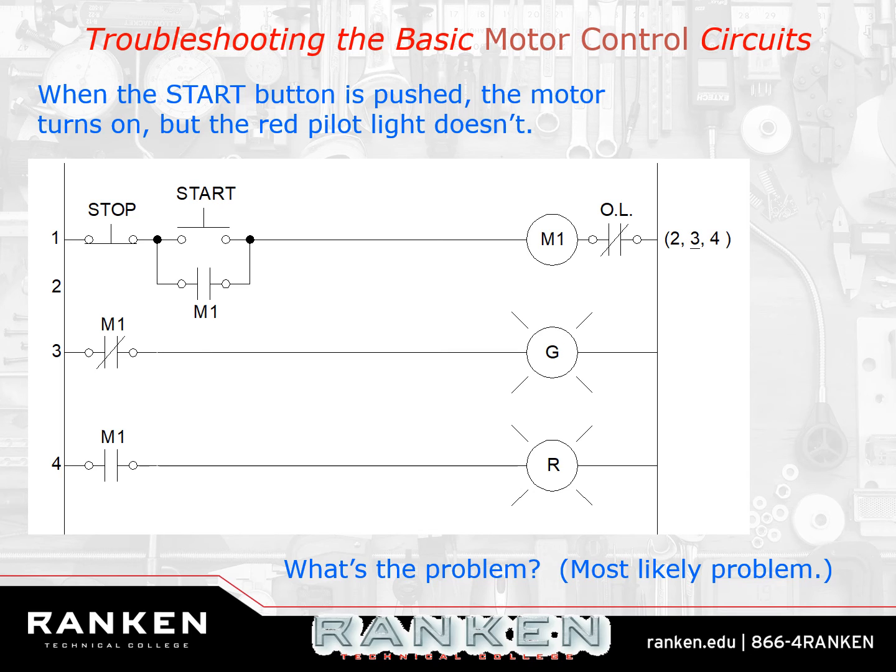What do you need to have in order to have voltage? You have to have resistance. Voltage only appears where there's resistance. So if I measure across this wire, there should be no voltage there, unless it's extremely long, right? Extremely long, 100 feet long. I might see a 1 volt drop, right? Voltage drop. But theoretically, I shouldn't see any voltage across that wire. But if I see voltage across that wire, that's an open wire. Or an open contact, or an open terminal block, or a bad terminal block, right? We have a bad connection.